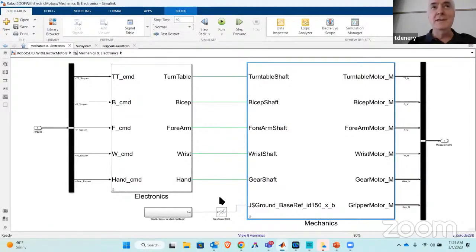Inertias we don't like to deal with because we have no intuition for them. Like I could pick up this laptop and tell you it probably weighs about 10 pounds, but I have no idea what its inertia is. Now, if I really did the math, I could probably come up with a base idea, but inertia is a tough one to deal with, right? So we love tools like SolidWorks that just give us a means to define the shape and do those calculations for us. There are absolutely some crazy conventions, where one person's version of the inertia tensor is a little bit different than another's. And you better know that when you program it into a tool like what we're looking at now that predicts the mechanical motion. All right, anyways, my main point is to get to this Arduino.